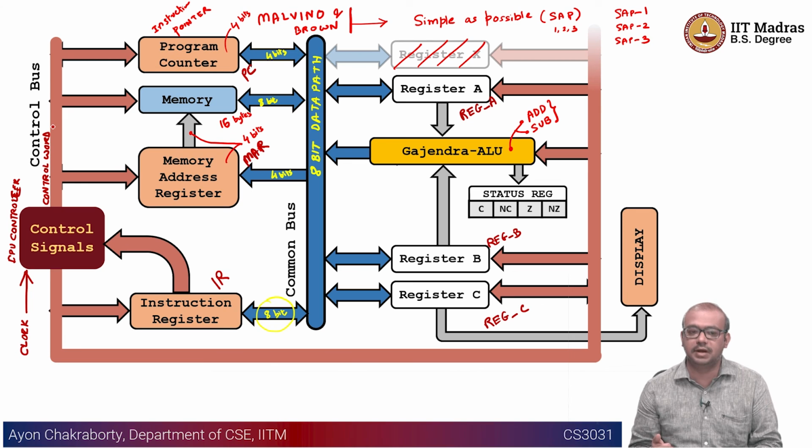Then what is going to be done? Then it is going to again increment the program counter, fetch the next instruction, and continue like that, right? So the control part is going to orchestrate how an instruction is executed, and of course how a program is executed overall, because it is also going to control the program counter, right?